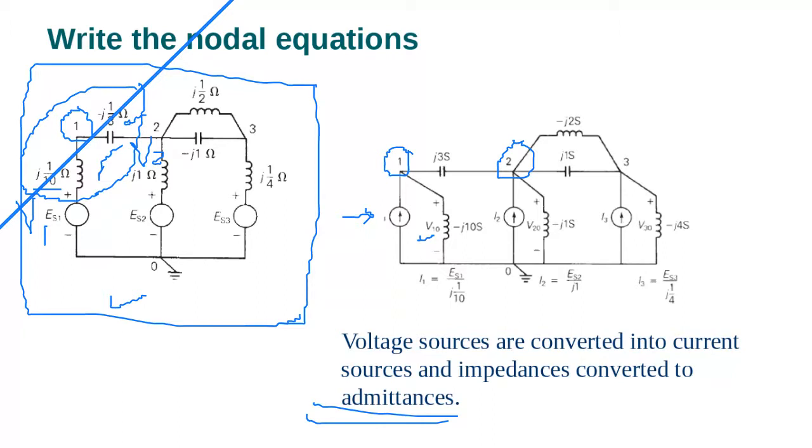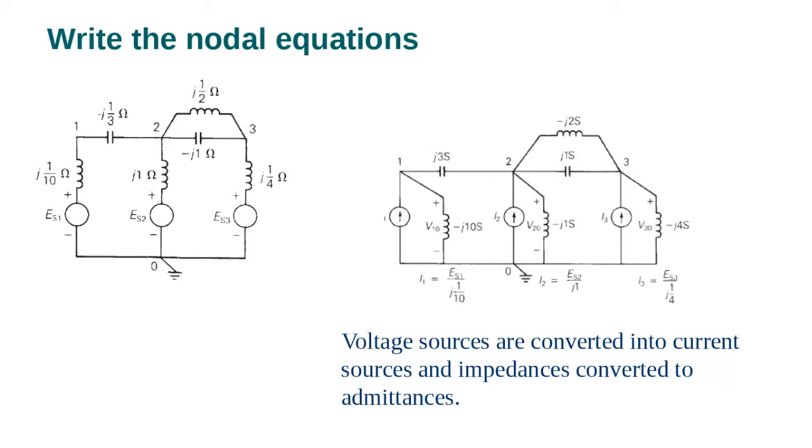Remember, please review how to convert a voltage source into a current source. This is straightforward unless you have a question that we can answer. When you convert this one here, you only take this part because I'm converting from 1. Therefore, I can just draw it like this, get rid of this, and make this a current. This is the way we do it.